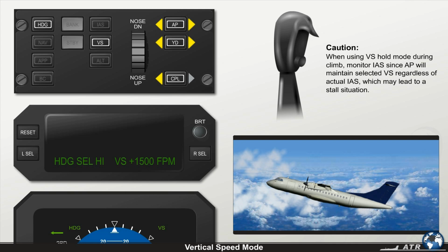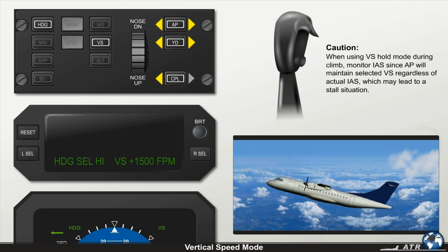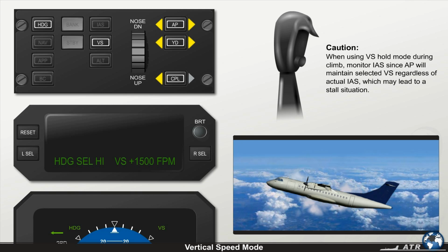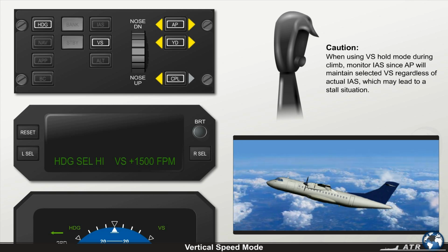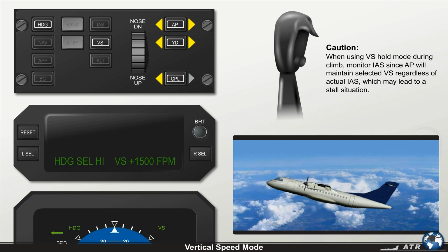Caution: when using the vertical speed hold mode during climb, the pilots must monitor the aircraft airspeed, since the autopilot will maintain the selected vertical speed regardless of the actual aircraft airspeed, which may lead to a stall situation.